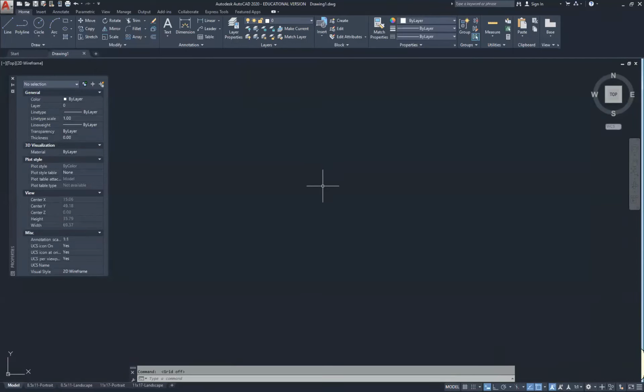So with that information, if I draw a line at 1, and then I go 1 down, I can connect those two lines with the end snap, selecting that object right there. And I can right click and end that command.